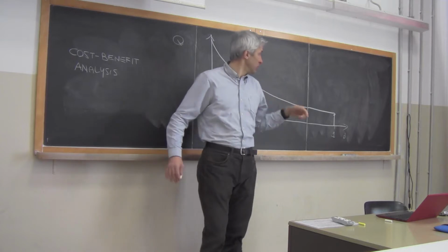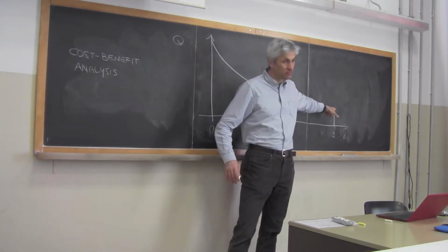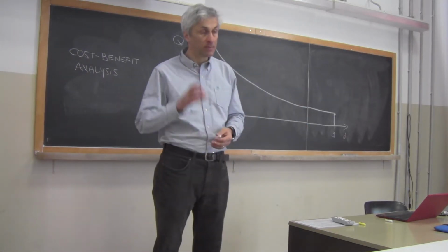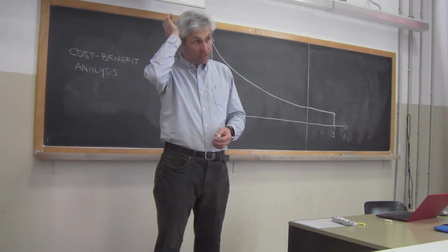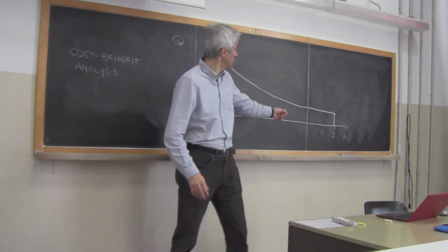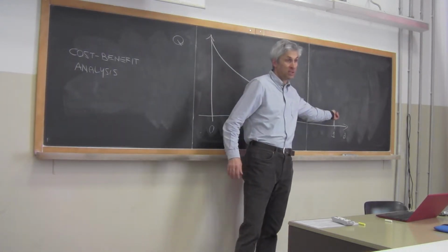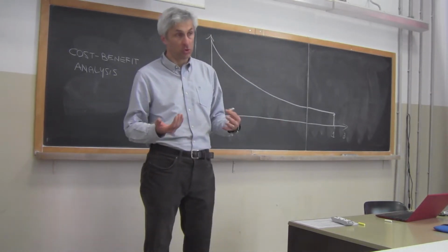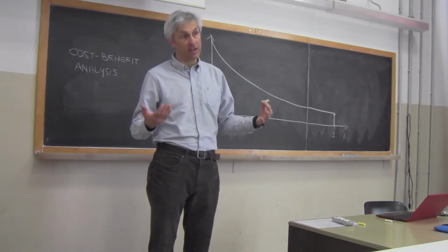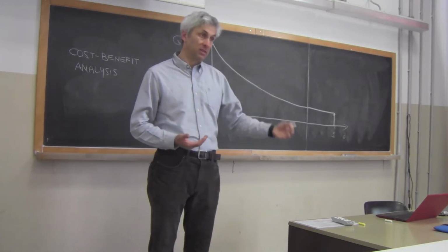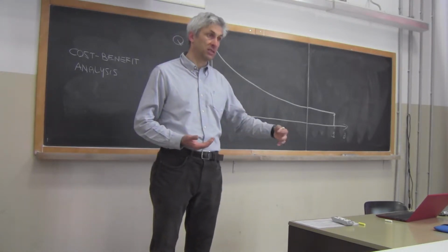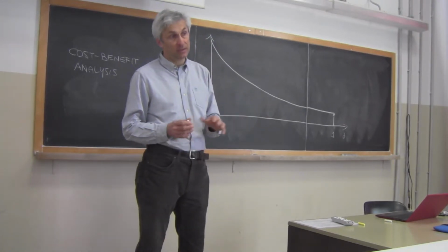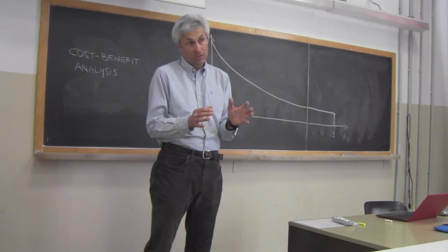On the other hand, if I go to the other extreme, I have a turbine that is working every day at the max efficiency, because this is a flow that is almost always present. On the other hand, the production of energy is very limited. So, for sure, it's not convenient. I spend less in building the plant, in maintenance, and the plant is working more efficiently, but it's a plant that works for a very small flow.